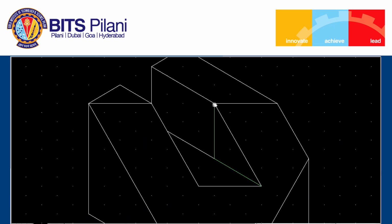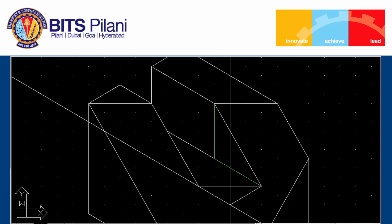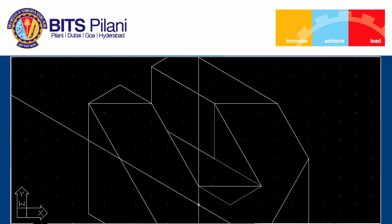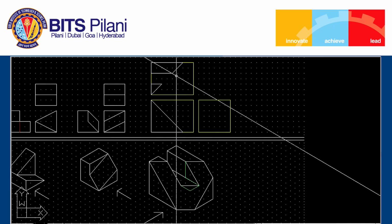From this corner I will be able to locate this point, 3 grid spaces down and 3 grid spaces along the length. In a similar way, this point, from this point I can locate 1, 2 grid spaces along the depth and 2 grid spaces along the length. So, that way we can locate these points. So, from this corner I cannot see the height dimension, but I see the length dimension.